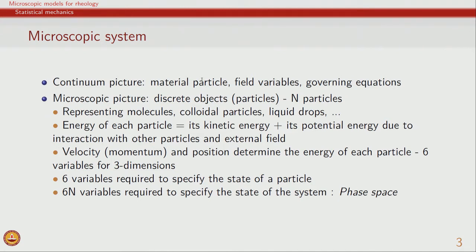Basically, between any two particles there are again infinite sets of particles, and because of the continuity of the field variables that describe the material particles and their attributes, we can then describe the overall relations between field variables using governing equations. And we saw that for rheometry, the mass balance and the linear momentum balance, or the equation of continuity and the equation of motion, were the two governing equations which can be used to solve all problems related to rheology.